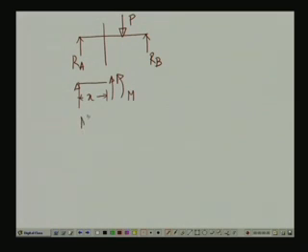So, the bending moment M is equal to R_A times x, which is equal to P b x by L, and the validity of this particular moment is from this particular point up to the load point. So, the validity is 0 less than x less than a.